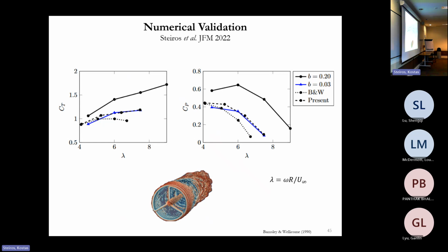What this shows is from the numerical simulations of the wind turbine. Here I plot the normalized drag, and here I plot the normalized power versus the tip speed ratio, which is how fast the turbine rotates. We performed the simulations in a very confined channel, as I showed before, and we got this power curve here, which is a solid line. Then we performed the same simulation, but in a much wider channel, which produced the blue curve here, right? Of course, as we expected, the power drops.